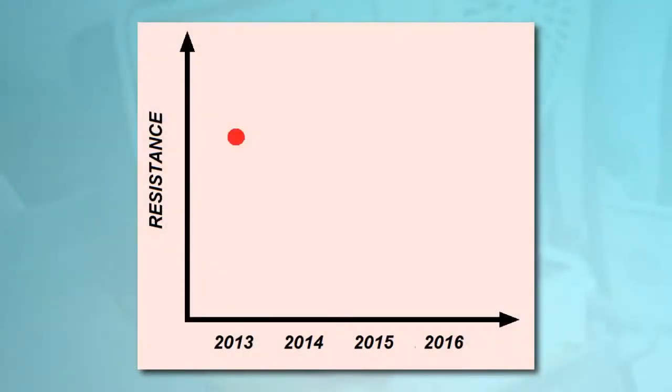For example, suppose you perform a spot test every 6 months. Plotting the results on a graph, you observe a slow and gradual downward trend, as would be expected by the normal aging of insulation. However, your latest measurement reveals a sudden drop in resistance. This is likely an indication that the insulation has begun to deteriorate at an accelerated rate. To address this, you can schedule downtime for the system and take appropriate measures such as cleaning, upgrading, or replacing the insulation.